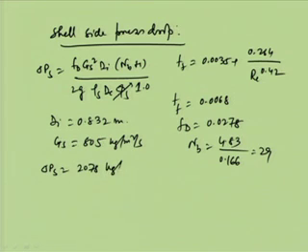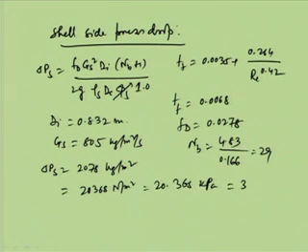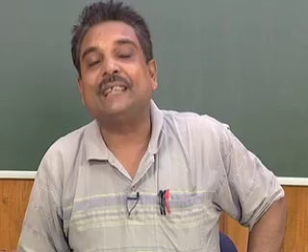2078 kg per meter square, and this is equal to 20368 Newton per meter square, equal to 20.368 kilopascal, and that is equal to 3.11 psi. So, 3.11 pounds per square inch. Normally up to 7 to 10 psi is the allowable range. So, we are much better, and it can be further improved, as more turbulence can be created to get more heat transfer coefficients. So, these are the possibilities.